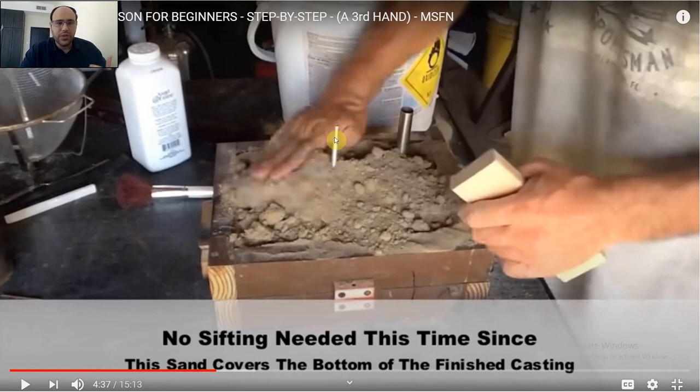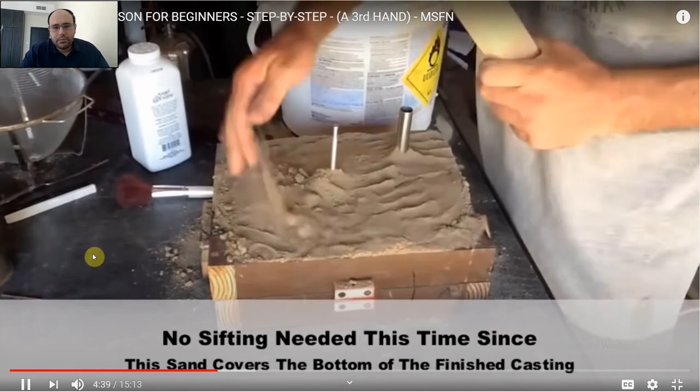But as I said, this is the vent which gets rid of the trapped gases inside the mold during the pouring process. And the other thicker tube, he's just making like a channel, which is known as the sprue, the down sprue, just to allow for the pouring of the liquid to fill into the mold cavity. But remember, we still have the pattern trapped inside the sand at this instant. So I'm just compacting all the sand.